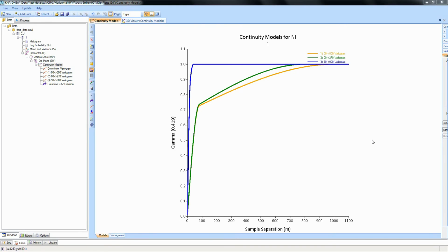To use these two modules in Supervisor, we're going to create two statistics. The first is the kriging efficiency. This measures the effectiveness of the kriging estimate to reproduce the local block grade accurately. The second statistic we're going to create is called the slope of regression, or the conditional bias slope. This summarises the degree of over-smoothing of the higher and lower grades.